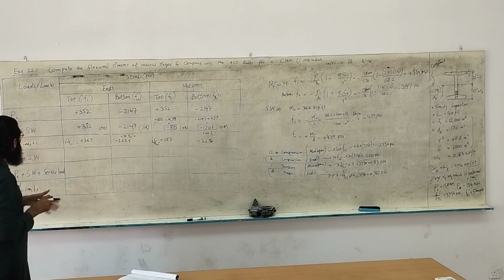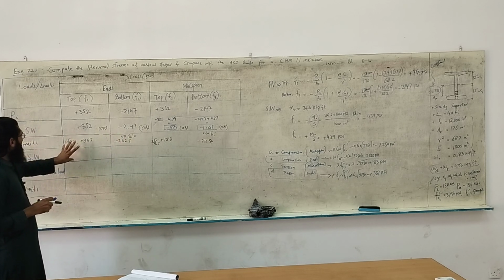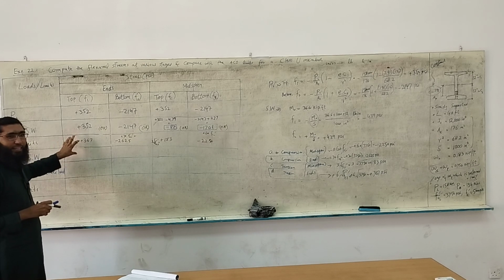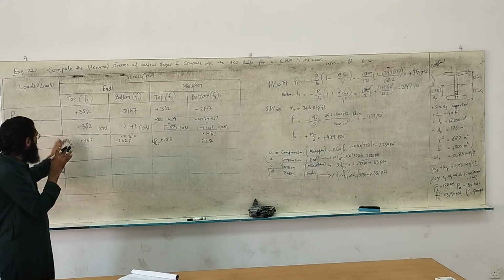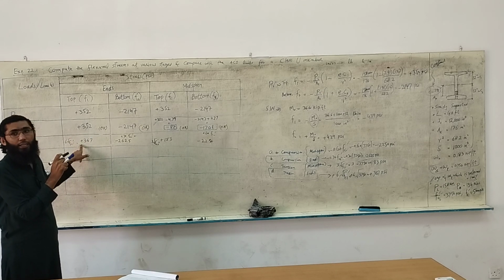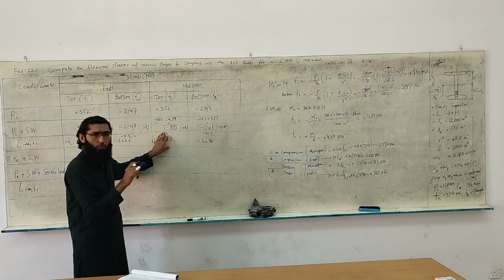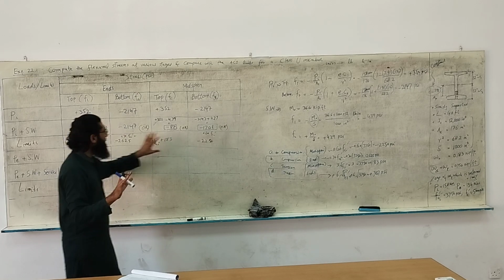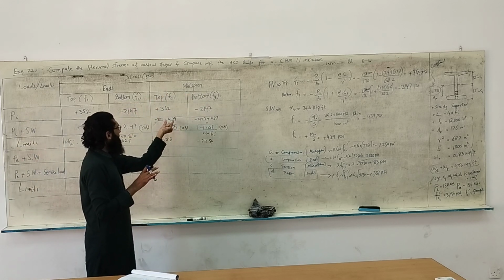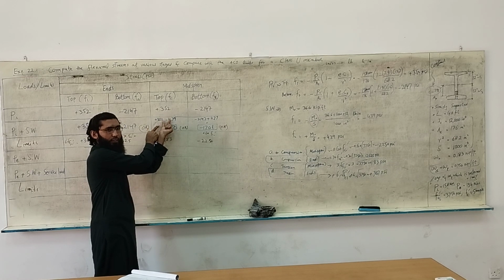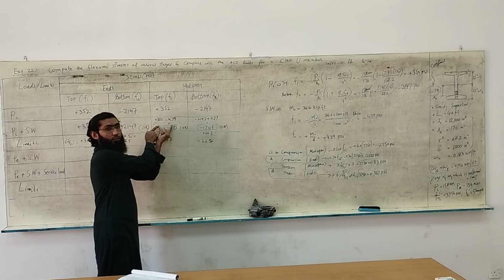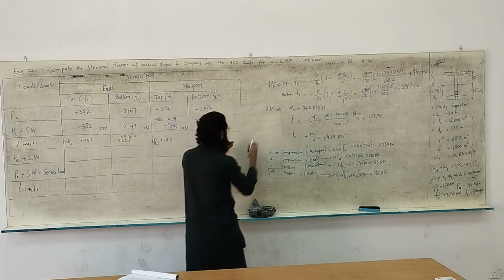As far as the tensile stresses are concerned, we have slightly relaxed limits for this case and somewhat more strict limits for this case. We are saying we will allow 367 psi at the ends, but for midspan, we won't allow anything above 183. Why? Because at the midspan, there will be some compressive stresses superimposed with the tensile stress due to pre-stressing, and the number will definitely be reduced. Okay, what I can say is, if this is the cross section, this